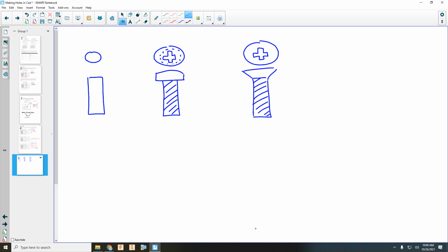Okay? And then what do our directions say? Our directions say measure, using a dial caliper, the length and diameter of the hardware to the nearest thousandths of an inch. So we want the length and the diameter. Now, what length and diameter do we want? Okay. On the pin, there's our diameter, and there's our length.